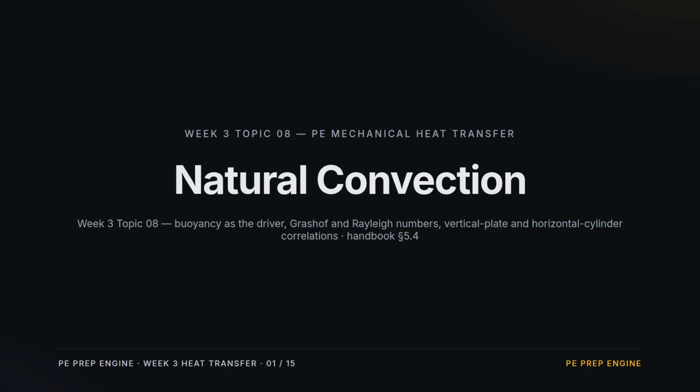Topic 8 of Week 3. Natural convection, also called free convection. The fluid moves on its own, driven by buoyancy, with no fan and no pump. We'll meet the expansion coefficient beta, the Grashof number, and the Rayleigh number. Then plug Rayleigh into the Handbook's power law correlations for a vertical plate and a horizontal cylinder.